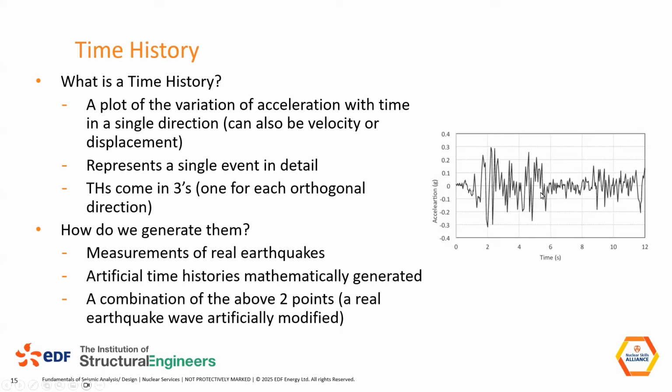It's a single event. So this is a very specific earthquake that is measured there. It's just one event. And we have 3 of these for any one earthquake, covering the 3 orthogonal directions. So there'll be one east-west, one north-south, and one vertical one moving up-down. So any single earthquake will have 3 time histories representing these 3 components.